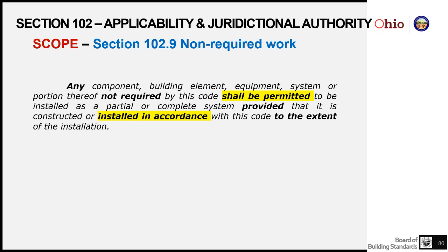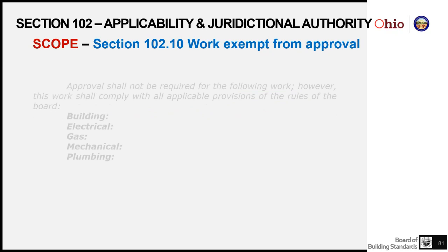Now, if you wanted credit on your height and area for sprinkled throughout and you only sprinkle 2 floors, you can't get that. But if you had perhaps a desire to have that ambulatory care facility on the 2nd floor and you sprinkled 2 floors, you'd be already set up to put an ambulatory care facility on floor 1 or floor 2. Might be some reasons why someone might want to do that.